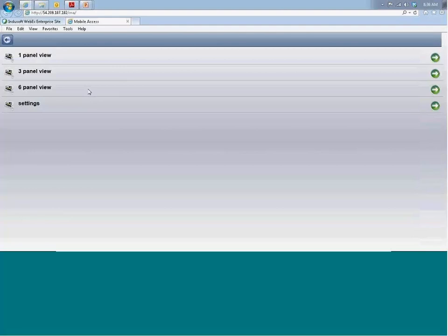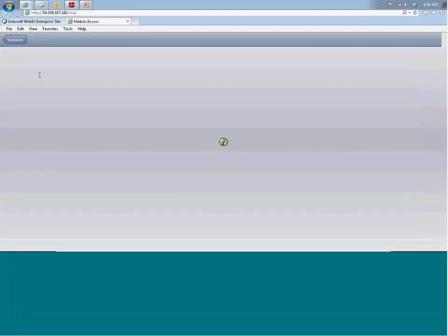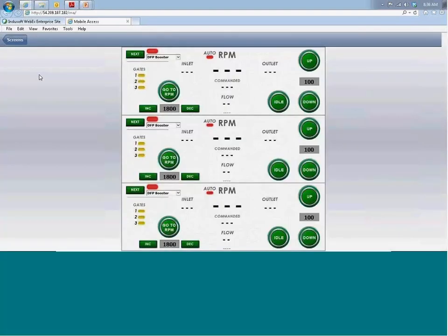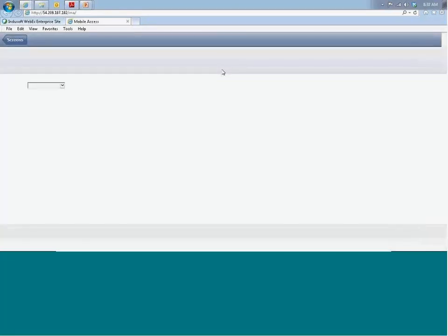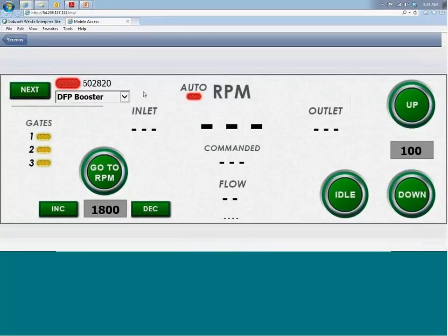Yes, actually, in InduSoft we have a very modular interface, and for data acquisition we have, in addition to the standard technologies like OPC-UA, XML, and so on, what's called native drivers that implement proprietary protocols. And when we worked with Dakota, they designed in their own RTUs a proprietary protocol which was quite efficient. And InduSoft developed a new communication driver specifically to support their protocols.